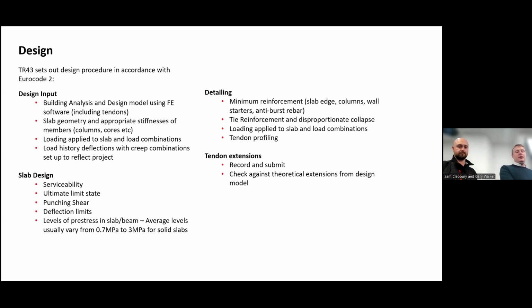We will set up a load history deflections, which is a system within RAM Concept, which is the program we use, which models the slab for its lifetime, and we can apply loads when they're applied, and the concrete will age and the E value will change over time as it's expected in real life.